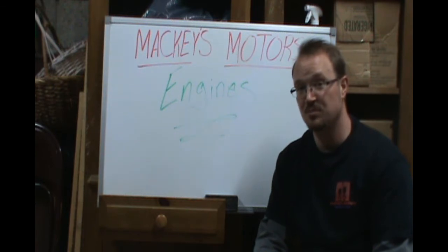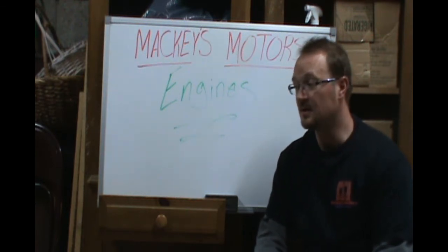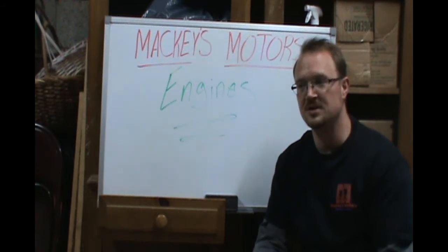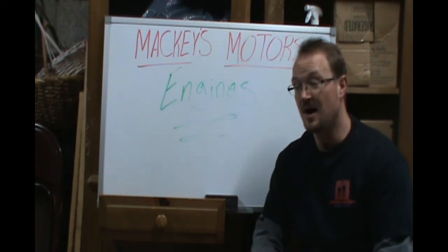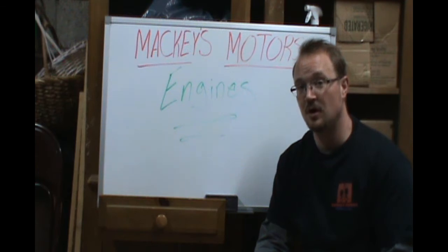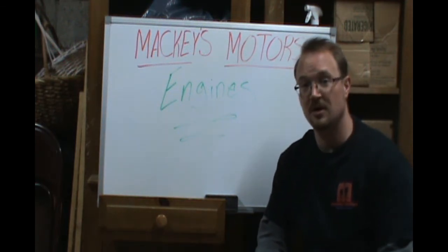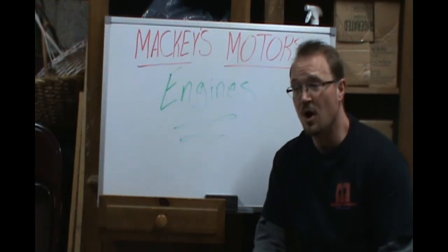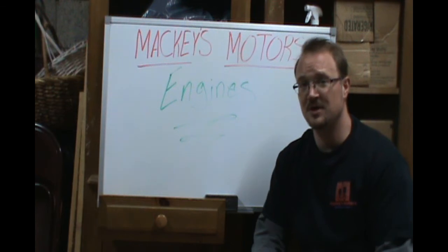Putting the proper spark plugs is one of the most important things. Running the proper fuel and constantly maintaining what is supposed to be operating properly. Changing air filters on a regular interval or even cleaning them out. I've seen a lot of people that can't afford a $50 or $60 air filter for their car. Take it, knock it on the ground, maybe blow it off with some air, and put it back in. Is that recommended? No. Can it help? Yes. But there's still contamination in that, and you don't want it getting inside your engine.